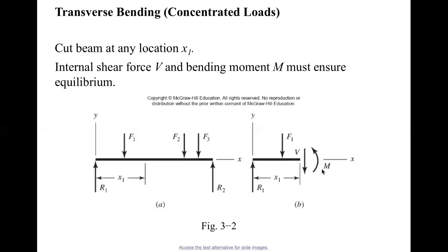Well, in order to find a bending moment, M, we don't know V, and it creates some problems. However, if you choose this location as the moment center, V goes through this point, so the moment produced by V will be 0. So in that case, we don't worry about V. If we choose the cutting location here as a moment center, you can write the moment equation.